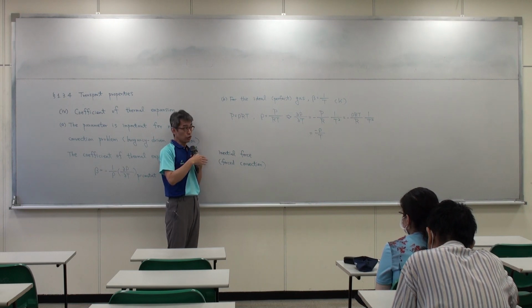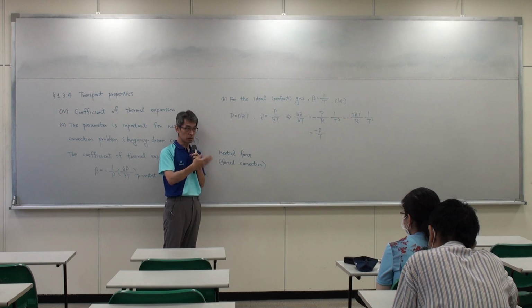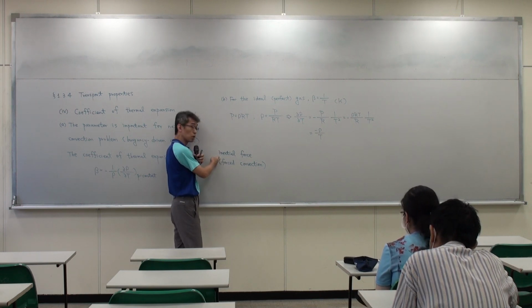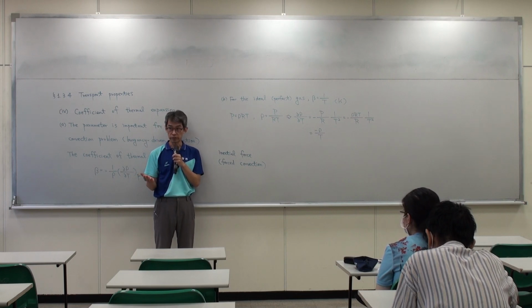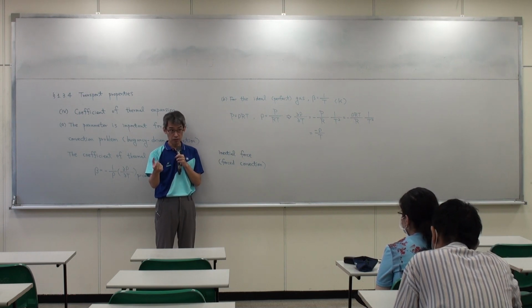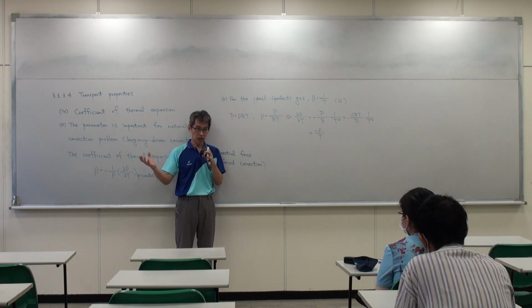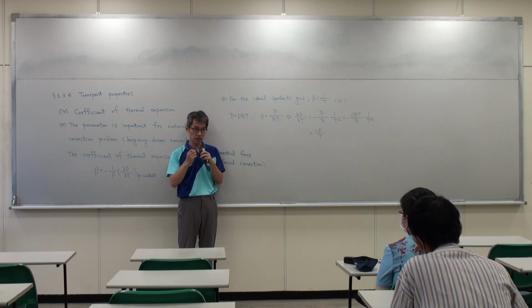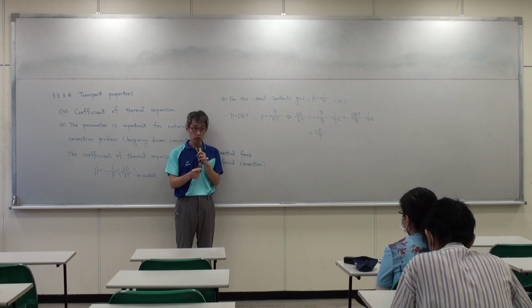So you can see most of the non-dimensional parameters relate to the inertial force. For example, the Reynolds number compares inertial force to viscous force. That means what kind of velocity comes in, and then how viscosity changes this original motion state.